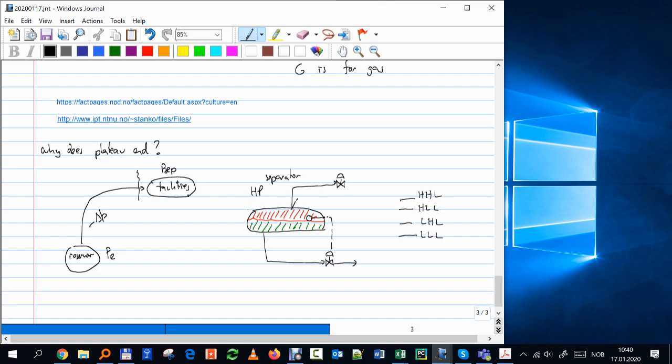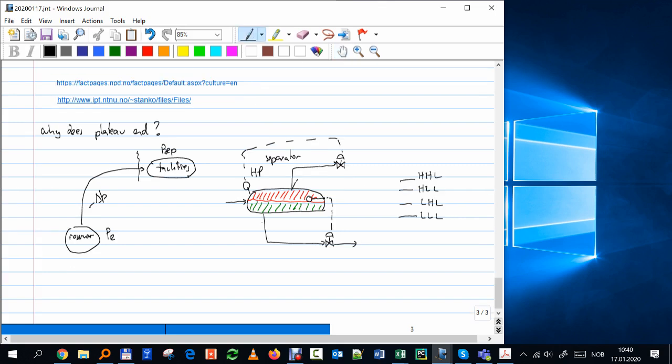Another control you have, which is important for our case, is this pressure. I have a pressure gauge, and the same thing: if the pressure starts to go up, I open the valve and let more gas go out. If the pressure starts to go down, I close it and let less gas go out. The reason for that is many of these devices that I have here depend on the volumetric rate. For example, the separator needs some residence time, so you need the fluid to have that. I'm not going too deep into this, but I think it's interesting.